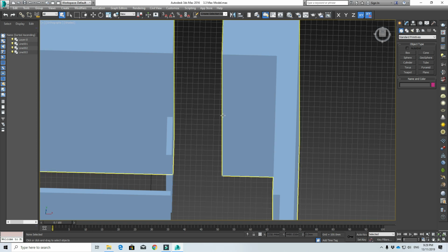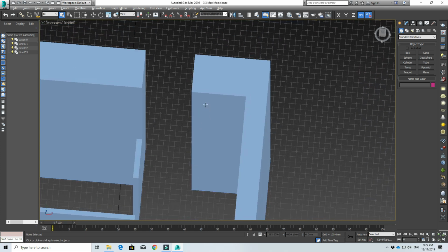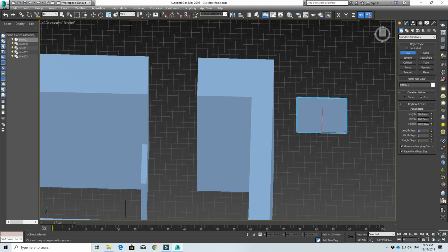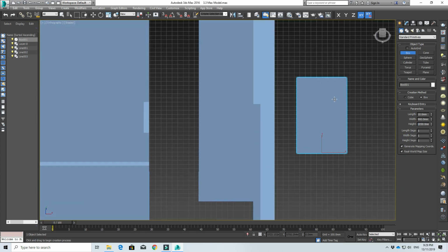So we just need to make sure that we know the height of 2050 mm and then close the gap above. What we can do is draw a box to simulate a door right now, because we don't have a model of a door. Let's just draw first. It's probably about 10 mm in length, 900 mm in width, and about 2050 mm in height. So this will simulate a door with a door frame.